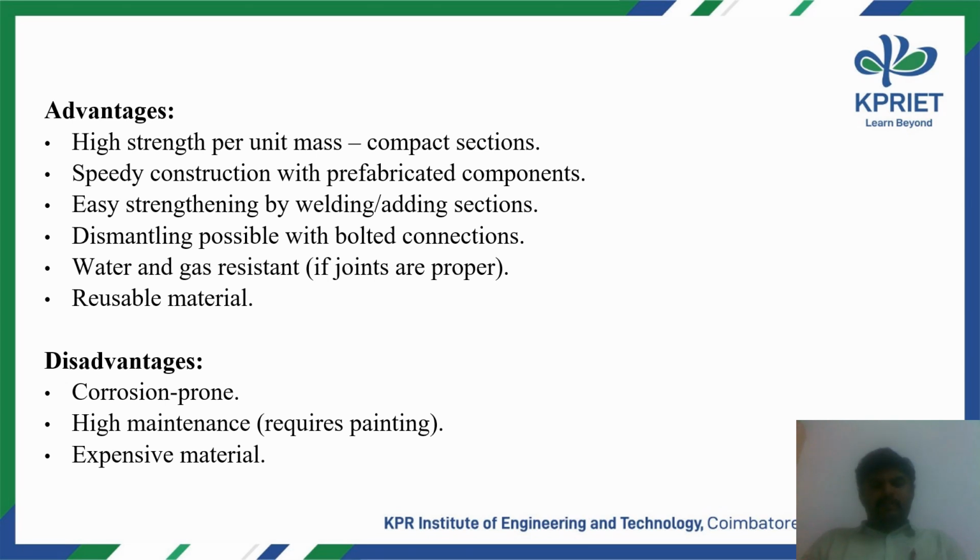The advantages of steel structures are high strength, speedy construction with prefabricated components, and easy strengthening by welding and adding sections. Dismantling is possible when compared to RCC, reinforced cement concrete structures. Also water and gas resistance if the joints are provided properly. And the best advantage is that it is reusable. The major disadvantages are corrosion, the need for periodic maintenance, and that the material is a little expensive.